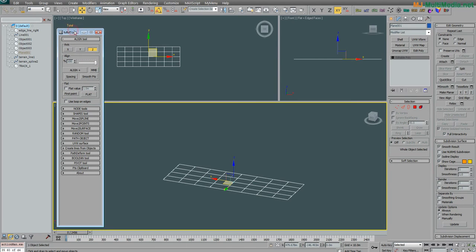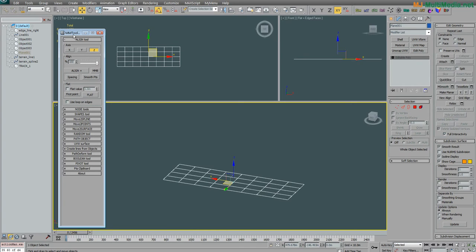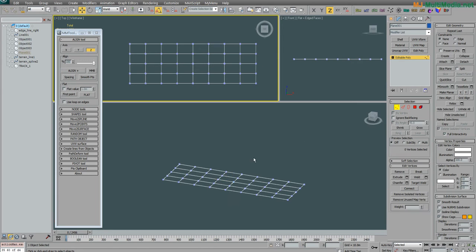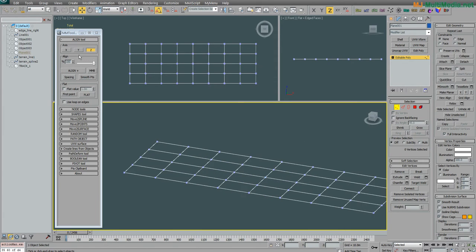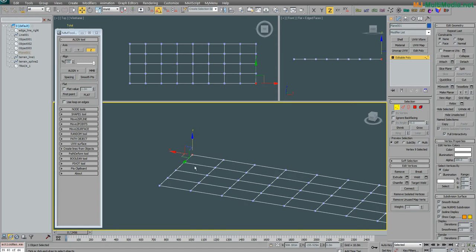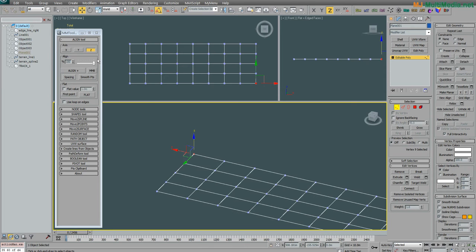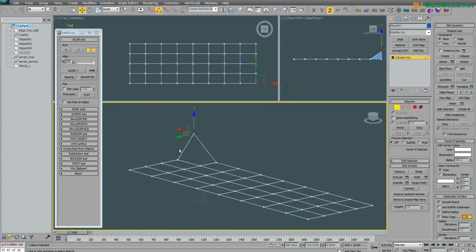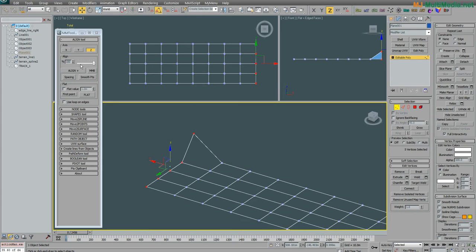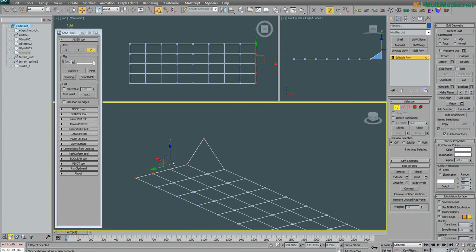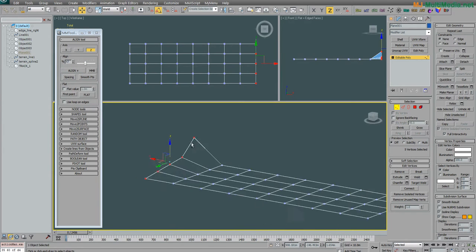This time I explain align, what you can do with it and all the possibilities. Okay, align. The most basic function is align selected vertex. We can, for example, in Z, if I move up, select the vertex and see, we get a line. With the middle value percentage, we get not a full align.